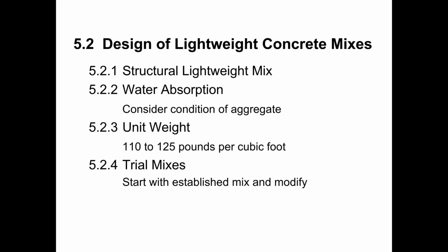And after a few rounds of trial batching using a supplier's template mix design, you should be in pretty good shape with your lightweight concrete mix design. So that's the recommendation. Instead of going through the tables in the book, you can do that. That works. But in real practice, getting a trial mix design from your aggregate supplier is probably the best first step.